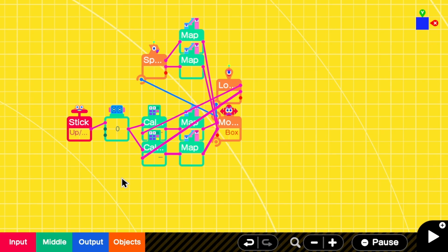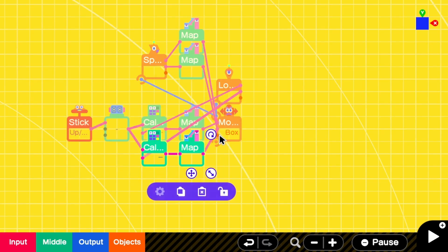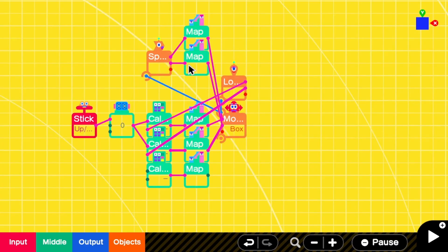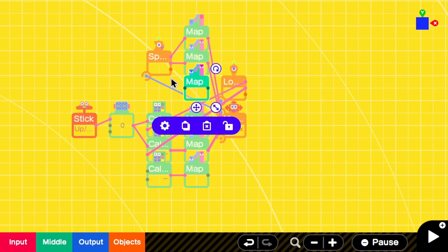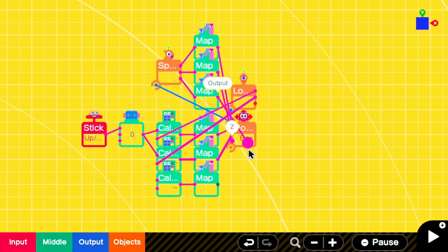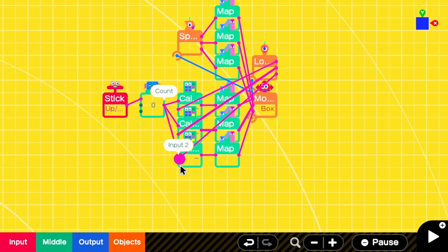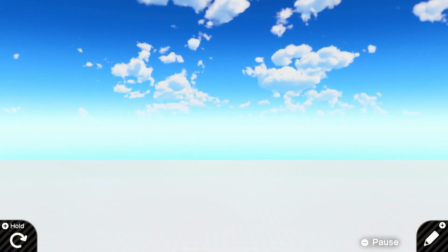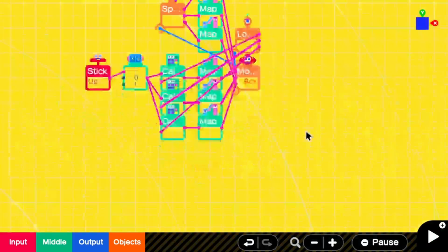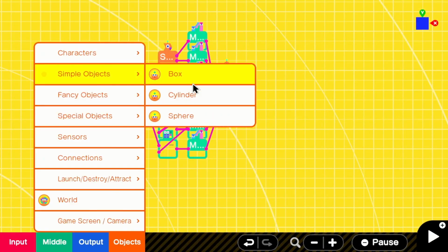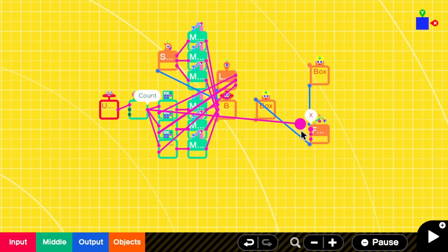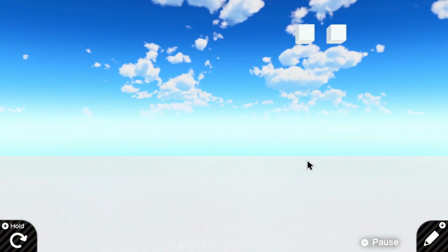And if we just want to make it on all 3 axes, we just grab this, the same thing as we did earlier with the Y. Grab the Z output of the location sensor here, Z input, and whatever position in Z that we want to control the moving box with. Here, yeah, now it moves in X, Y, and Z. And we can compare it with the free slider here. Same values, and we can see them both at the same time here in all three axes.